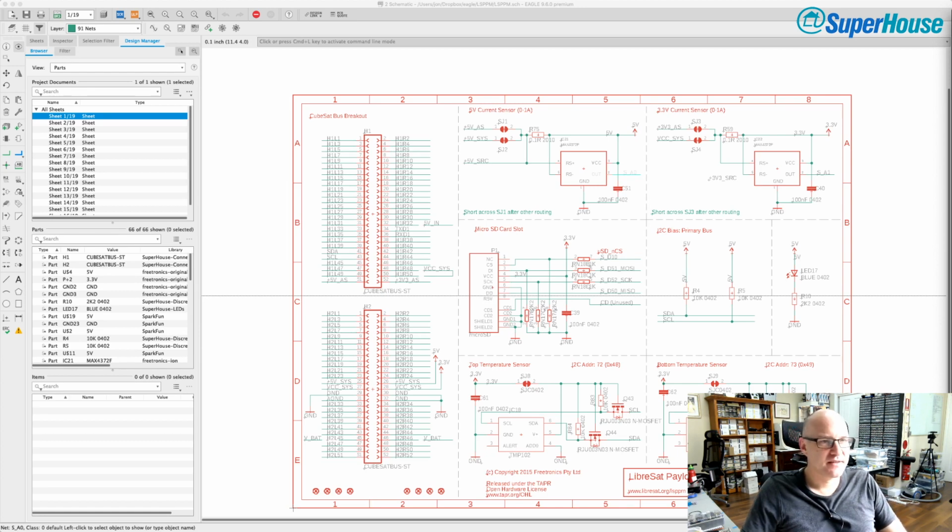Alright, Martin said, with AC power monitoring in Melbourne and smart meters, can't you monitor power over Zigbee? That is a very good point. And yes and no. What you can do is monitor the overall power. Typically, if you have a smart meter, that is a single entry point into the power system of the house. So the meter is kind of at the demarcation point between the power company and your own internal wiring. Everything from the inside of the meter is your responsibility, from the outside of the meter is the power company's responsibility. But everything has to go through the meter, which means you get one number, and that is the total power consumption for the house.